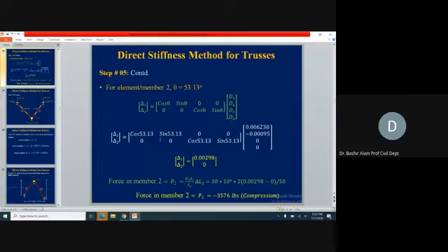So here I'm putting now in the transformation matrix these values. D5 and D6 already we found. D3 and D4, those were 0, 0. So I'm putting those 0. Now the product of these two matrices, so delta 1 is coming equal to 0.00298. We are going at least up to 4 decimals now in finding out these deltas. Delta 2 is coming equal to 0, 0. Why? Because 0 multiplied by 0, this is 0 and this is 0.